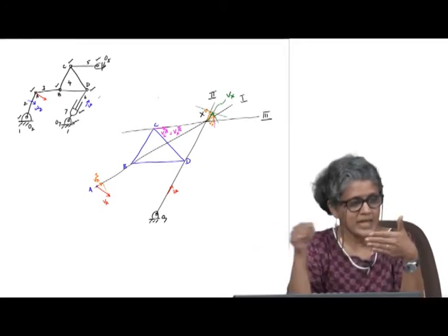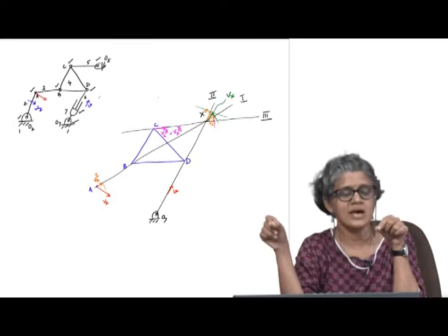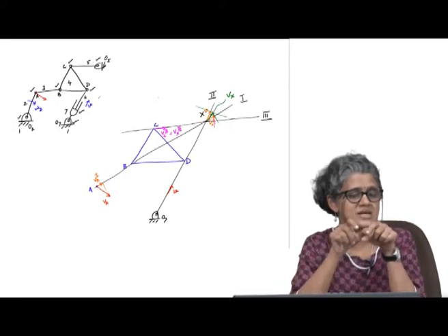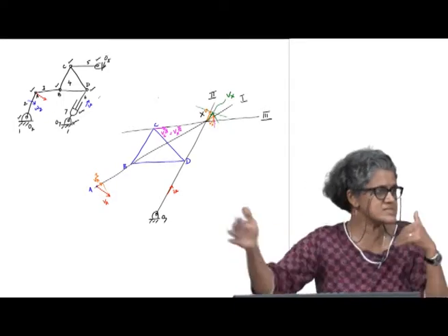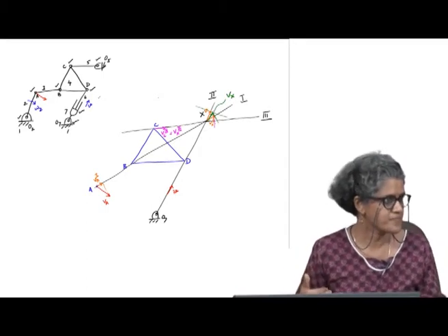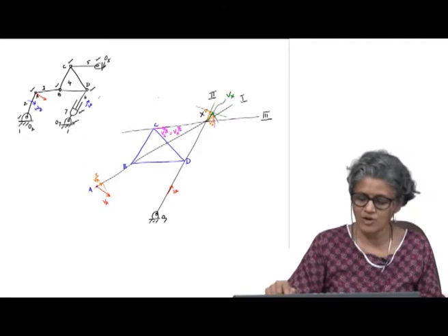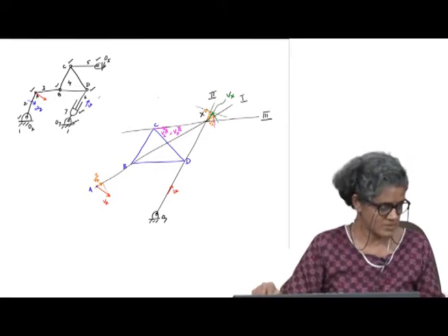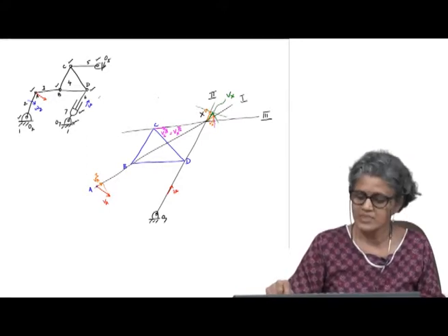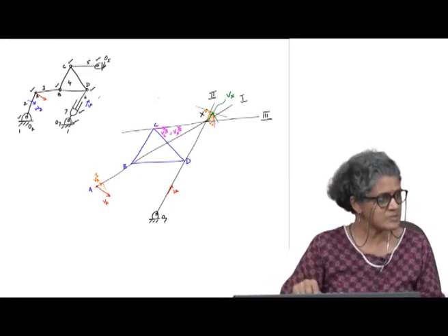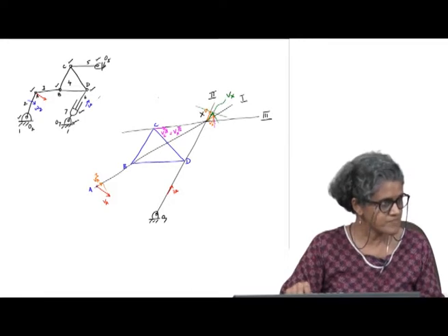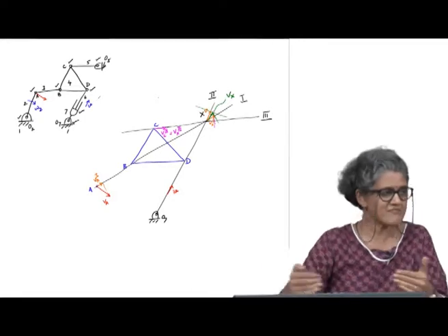So, if you take any line, the velocity that is transmitted has to be equal, because the distance between those does not change. So, if I know the velocity of x and I draw the auxiliary line Cx, then this velocity Vx along 3 will be equal to Vc along 3. I am kind of working backwards now.